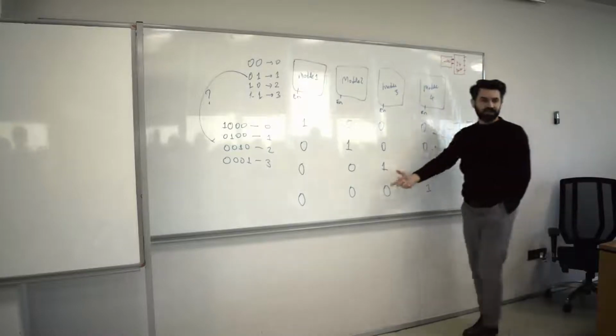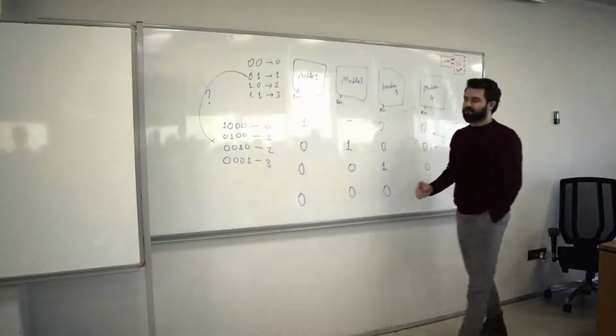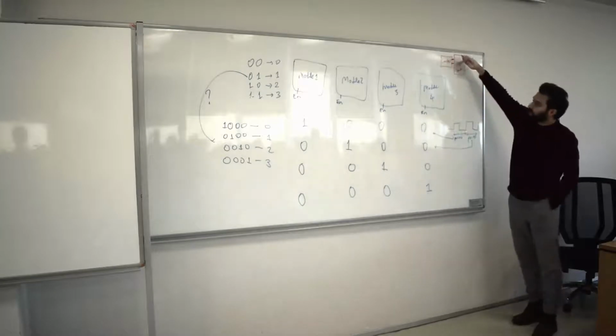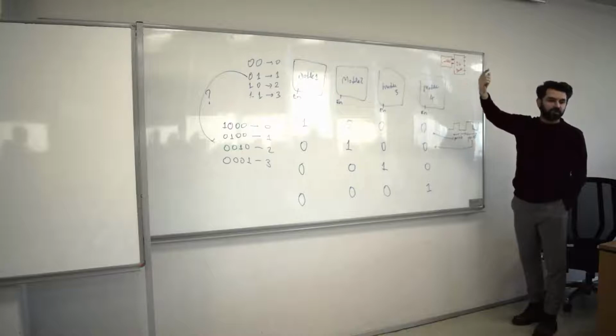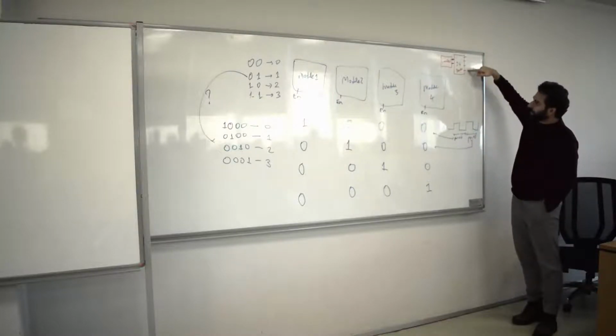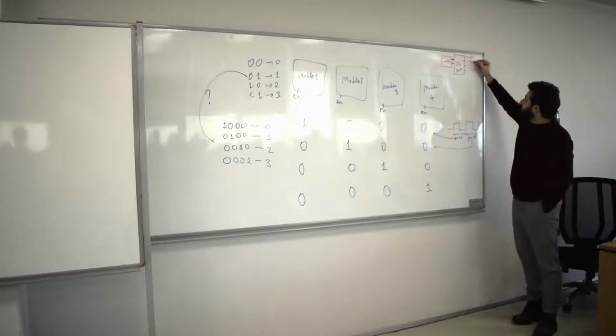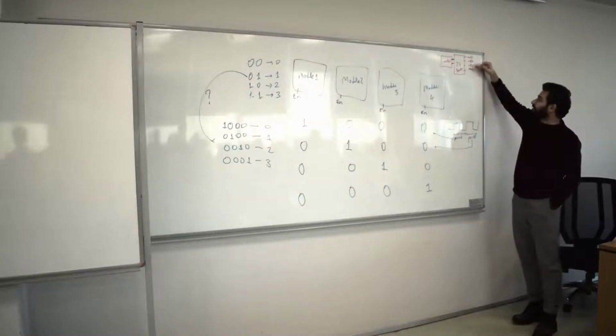And that's exactly the description of the output of a ring counter. So as you count here and generate those binary bits, 2 bits, this would generate a 1 that is circulating. If you put, for example, a LED on each one of these outputs, that LED would go around in a circle.